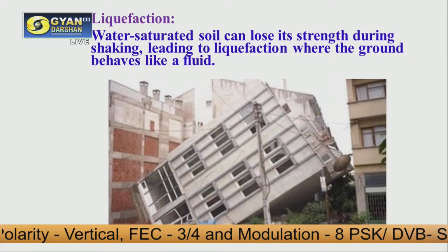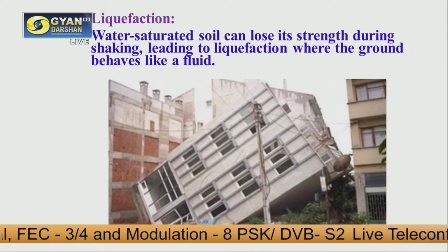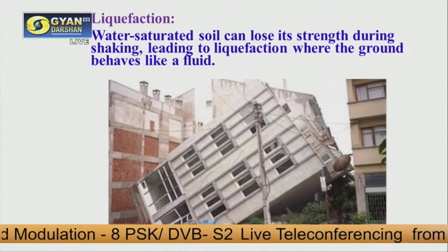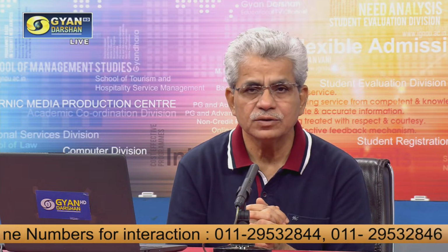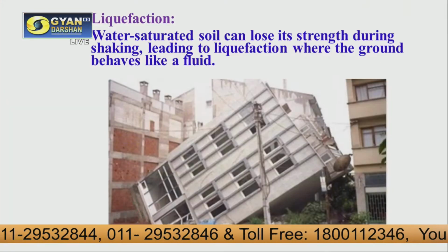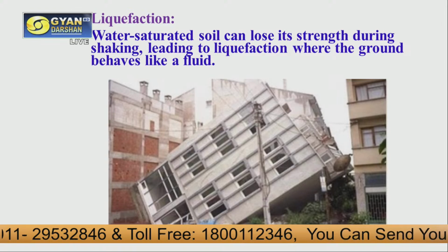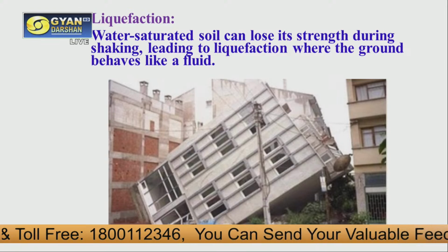So this is happening because of that excessive shaking, because of the earthquake. And if this shaking is done in that saturated sandy region, then the soil may lose its strength, and this phenomenon of liquefaction occurs there. And if some structure is there in that area, that structure may sink into that sand, into the ground basically. So as you can see in this graphic, part of a building sunk into the ground because of that liquefaction process.